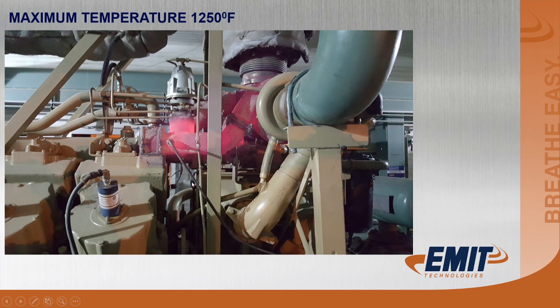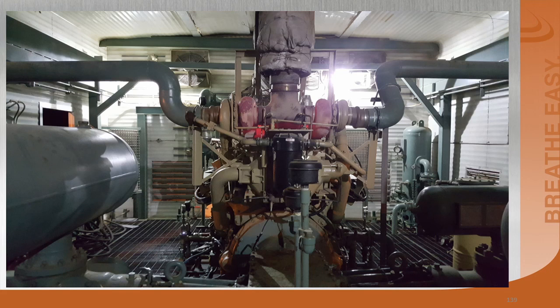This one has remote mounted O2 sensors. This transition manifold right here is where Waukesha puts an 18 millimeter port. This is not a good spot for an O2 sensor. They don't survive. So what we've done is moved this O2 sensor around to the back side and then brought the return off of that line here. And it's a remote mounted O2 sensor, and we'll talk about them more later. Okay, here are the remote mounted sensors right here.